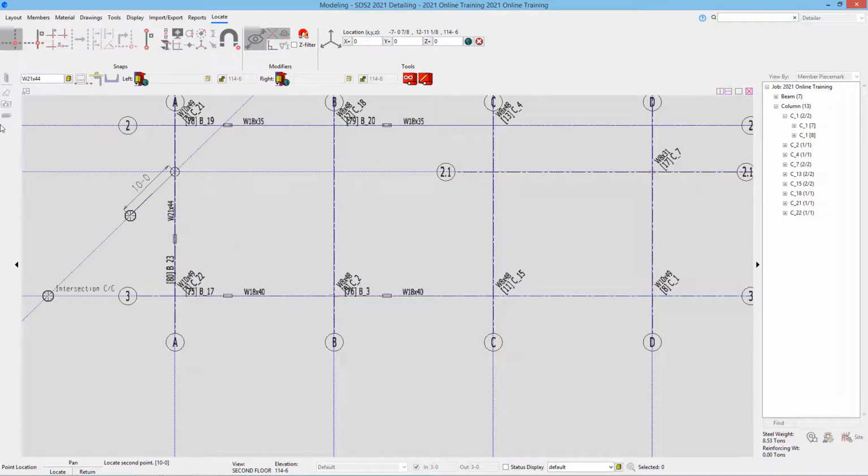I can then go in and snap to those different locations. You can see it snaps on 45s, the exact points, or the intersection of construction lines. If I knew a direct angle, I could go in and type in the @ symbol and type in 30 degrees, and now it's going to put that at 10 foot 0 long and at 30 degrees. So our typed dimensions can be used with any member type that we are working with here. If I decide I don't want that, I can just hit the backspace and clear that out.